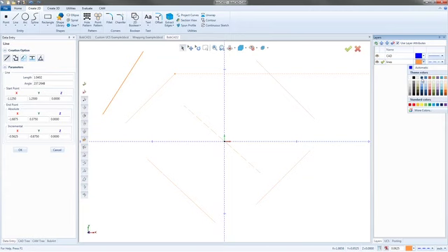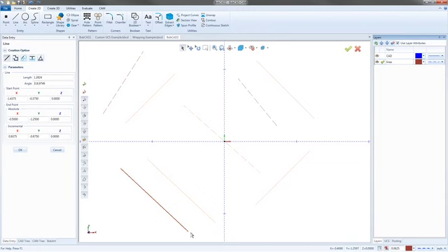So now if I go change my color, I'll change it to red. We can see it changes the color, and it's still going to be a dotted line. So the layers can help you keep things not only separate from the fact that they're on separate layers that you can now turn on and off as needed, but the big thing is you could change the colors, and you could have each specific layer match colors.